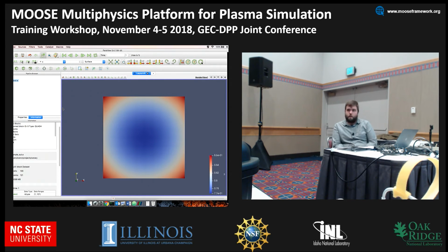But now that we've got that, we need to create. So for your reaction term, the default coefficient is 1? The default coefficient is 1 because you don't provide it. There's no parameter to define a coefficient. So in this case, since we have coincidentally defined our coefficient as 1, we don't have to write new code. But if I said it was 2, or something, our constant times reaction and compute QP residual would need to return that.